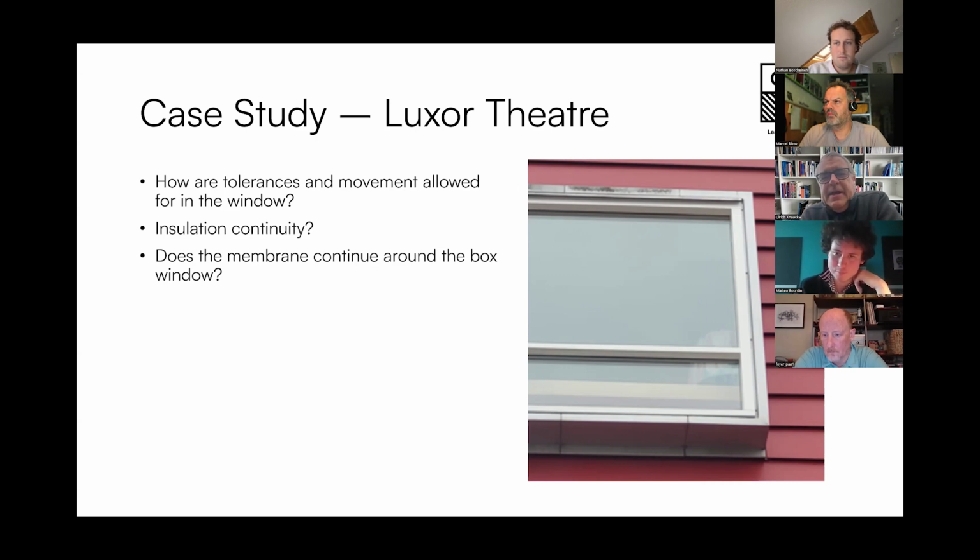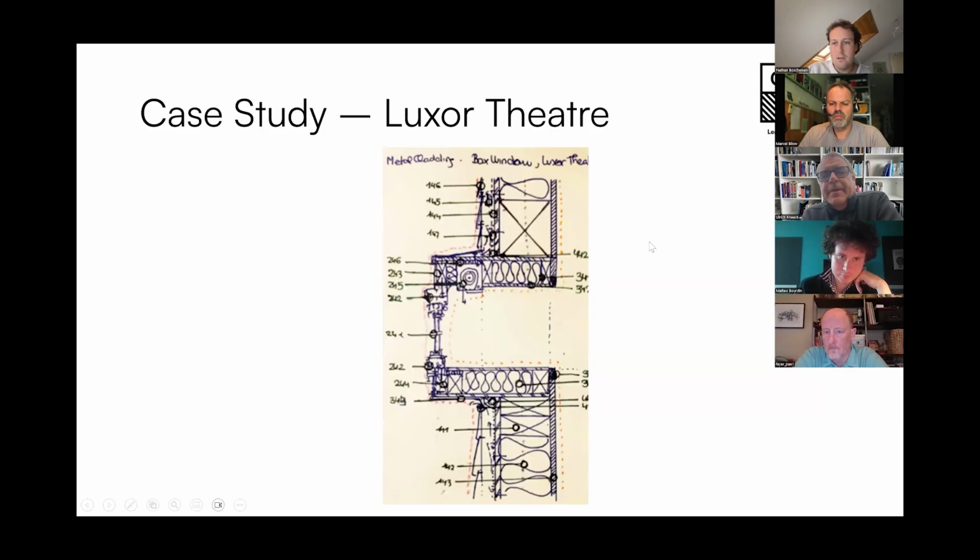And we see the detail you drew. Nathan, I'm sure you have it somewhere. This one? Yeah, this one. So this is what you assume this is made of. Okay. And we see a timber cladding at the outside. We see a substructure. Then we see an outer layer, insulation, an inner layer, gypsum board, I guess. And then you drew these boxes. And the top part of the box, drainage is taken care of with a metal sheet. Okay. And then there's this shading device which is integrated.